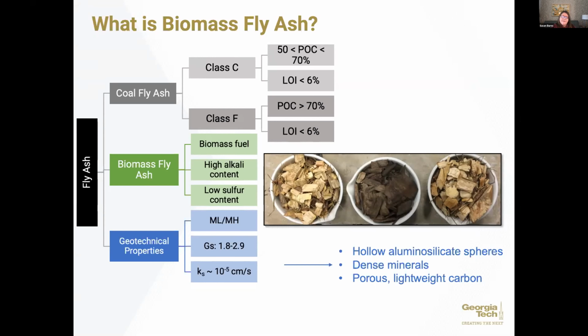Generally, we're going to have a specific gravity on the order of about 1.8 to 2.9. And this will be a function of what minerals are present in the ash itself. We've done some experimentation looking at conductivity as well, and you can see a conductivity for these silt-sized particles of about 10 to the -5 centimeters per second.